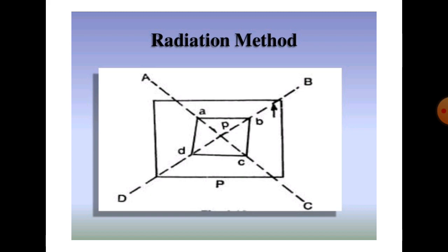Then fix the alidade, or touch the alidade at point P, and from the eye sight to the object, bisect the point A ranging rod. So here an imaginary line is drawn from point P to point A as a dotted line. Clear? So these lines are dotted or light lines, drawn from point P to point A, but here measurement is not taken.